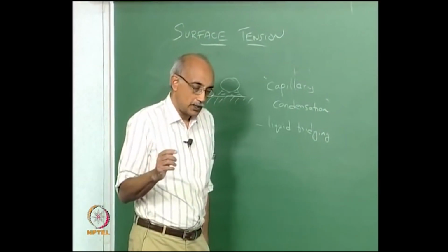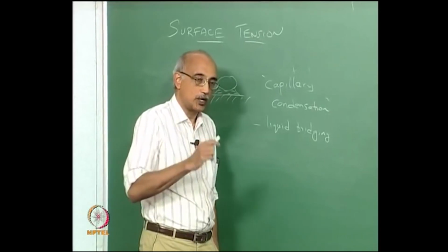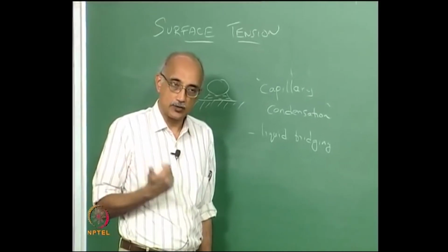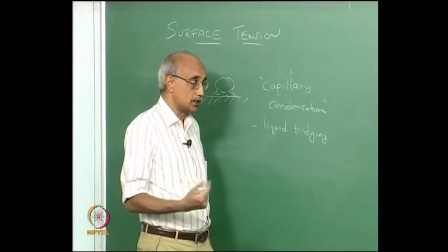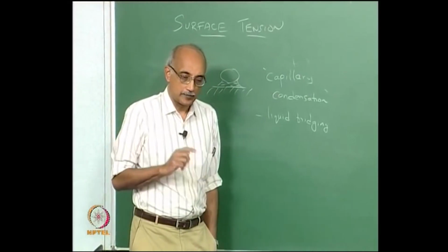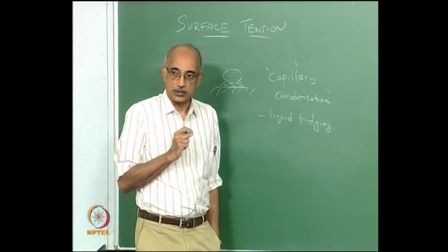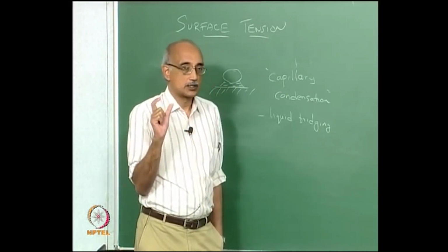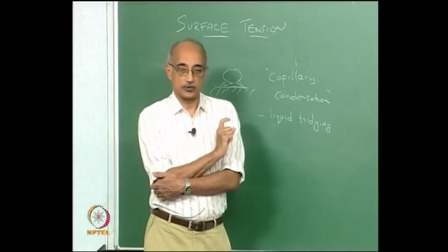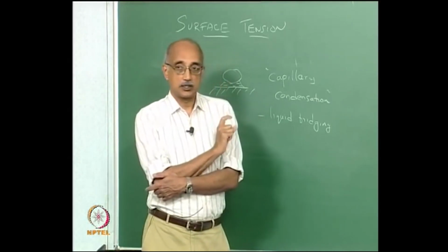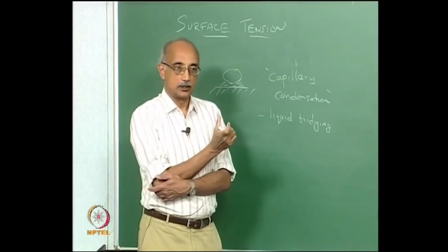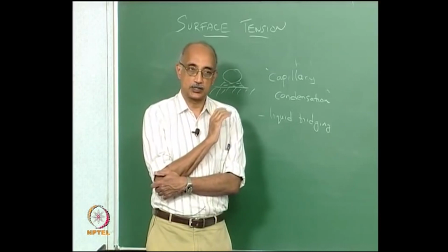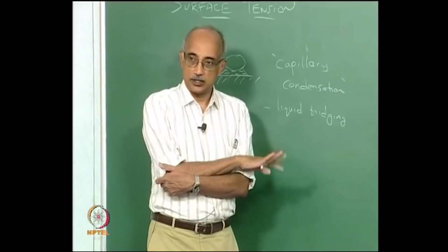Again, the reason why it is easier to remove particles from a surface when it is immersed in a liquid, as we saw yesterday: the first reason is van der Waals forces are reduced. The second reason, which we did not talk about earlier, is that the contact potential forces, or even the Coulombic forces, all have the dielectric constant as one of the terms. The dielectric constant of water relative to air is 80 times. So, if you look at the equation for the forces, the dielectric constant appears in the denominator.